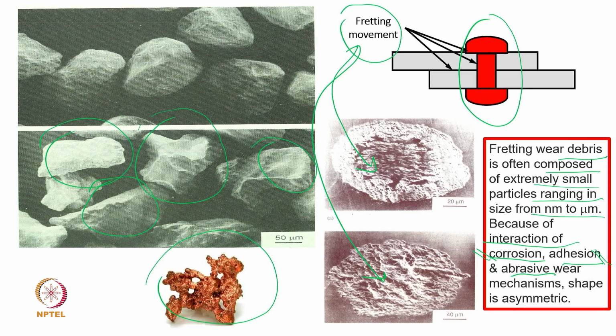If there is fatigue wear, I should stop it or maybe tighten it. That is why many times we say that whenever there is a nut and bolt connection, there should be regular maintenance. What is the meaning of regular maintenance? Many times we open the bolt, we oil the bolt, and then again we close and tighten the bolt, so that sufficient torque is there and the bolt is not getting untightened.